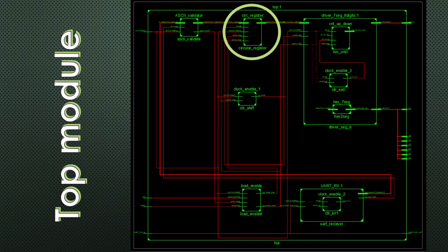That one is filled with 1s because that's the ASCII code for white space, which we need for the start of the next process. Resetting the module has a similar effect as initializing it from the very beginning. When we load wanted data to this register, we load them synchronously to all 8 registers, always to the same position. After this process, the stored data position index is incremented.